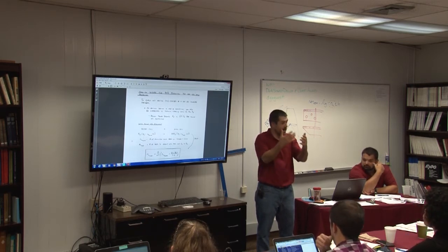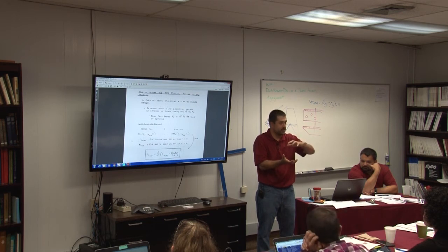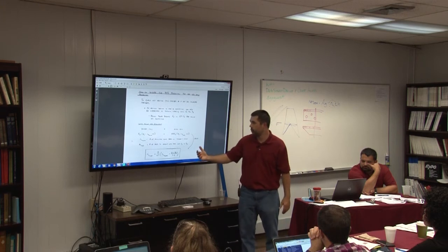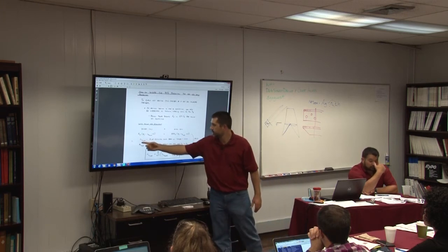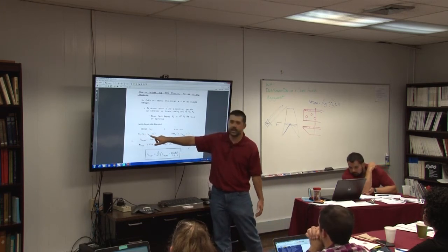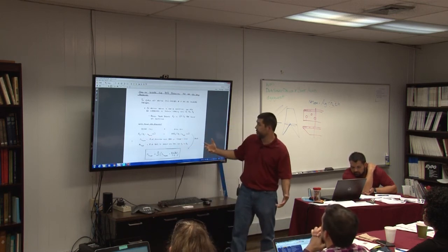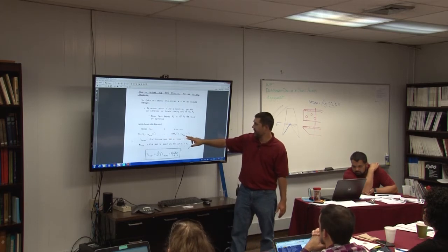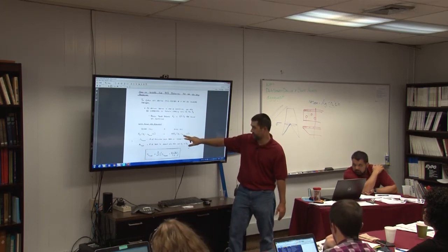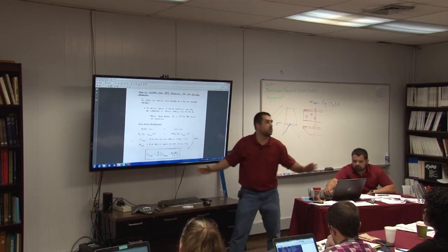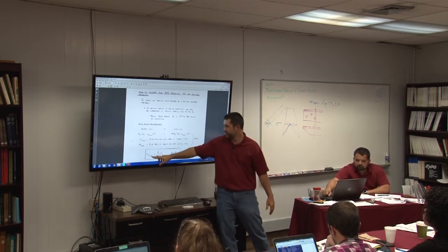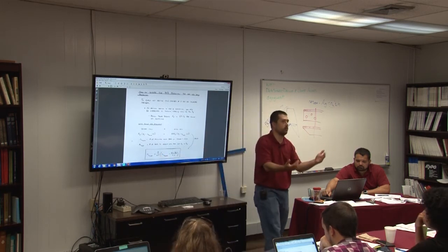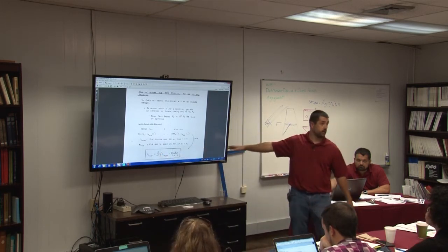But if you're in the middle of the member, you can kind of assume the full cross section has been engaged. So you can actually adjust the number of holes, right? My desired calc is to use the full Fy times the calculated number of holes. What Tower is really doing is using 0.9, and so I want to calculate an adjusted number of holes such that these two things are equal, right? So my final adjusted number of holes is this equation, which is, again, based off of the calculated number of holes in Tower.